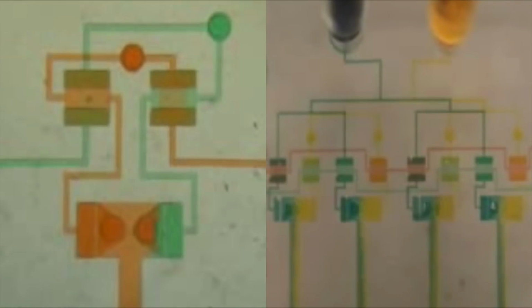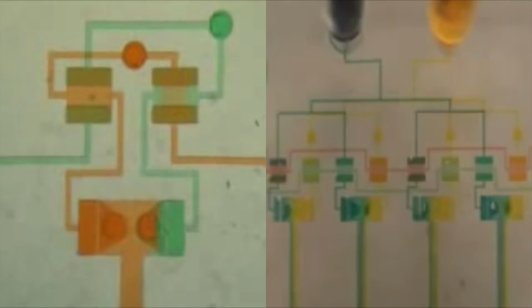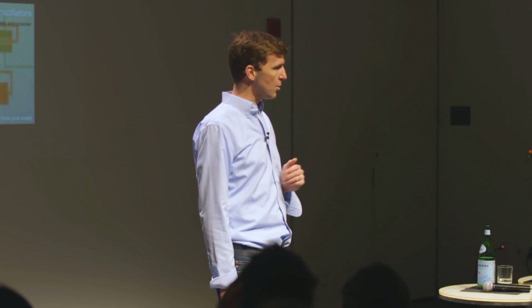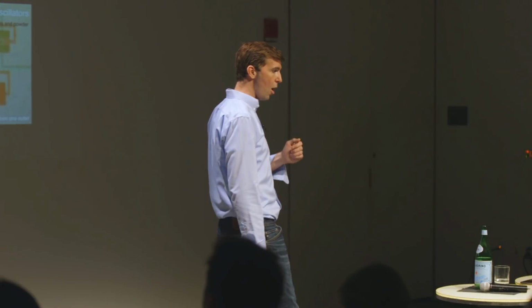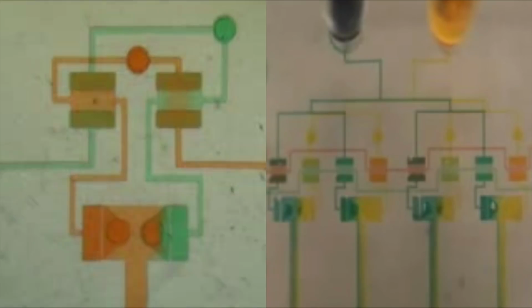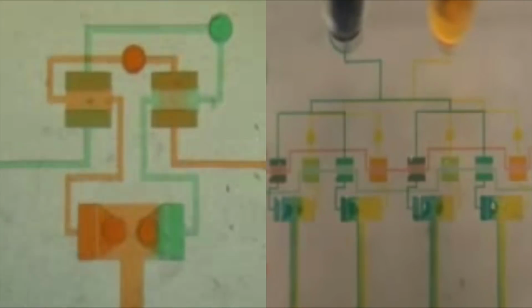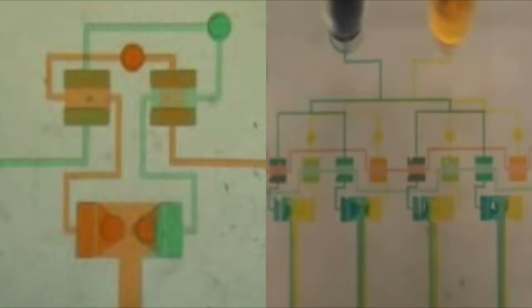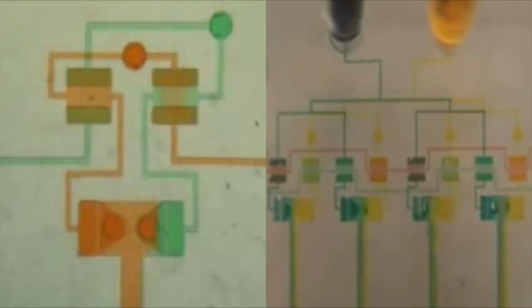And so it turns out you can use microfluidic systems to create almost any sort of copy, in a loose way, of any electrical circuit that you might want. Circuit components, resistors, capacitors, and even higher order things like digital logic and sequencers, counters, comparators, whatever. I can do that all in fluidic systems. This is an example of what we used, which is a very simple example of just a fluidic oscillator. So I pump in a constant positive pressure, and the output is basically an oscillation of pressure on multiple outputs.